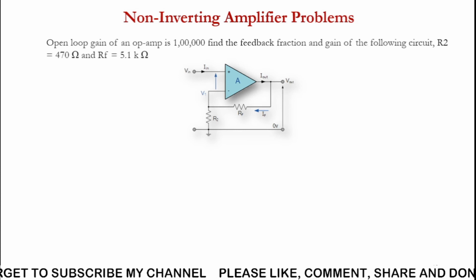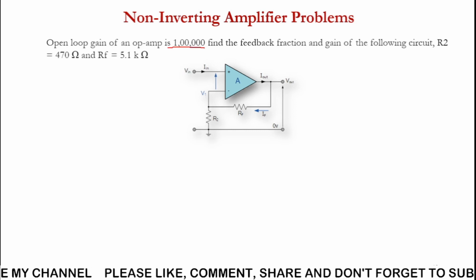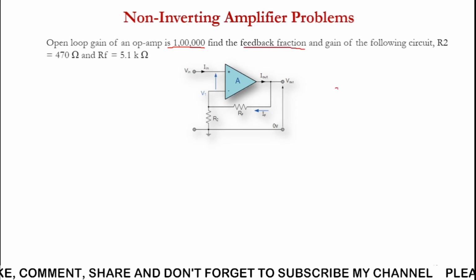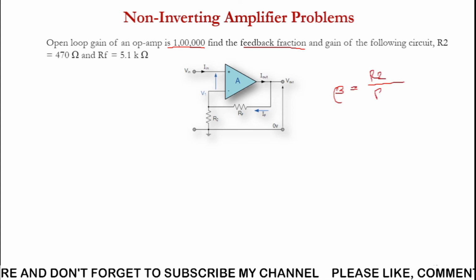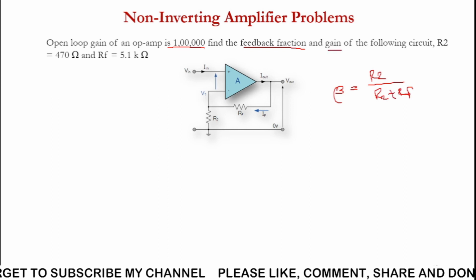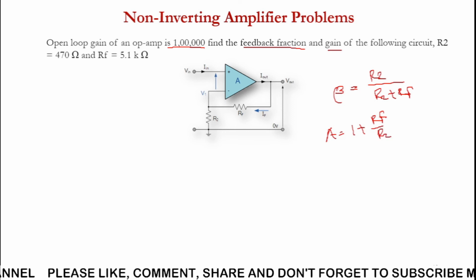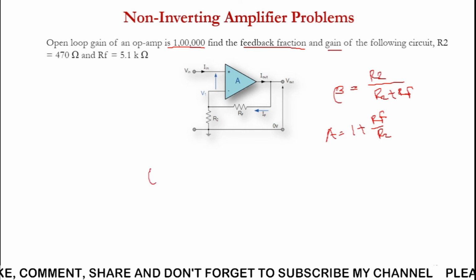So look here, a non-inverting amplifier problem, where the open loop gain is 100,000. The open loop gain does not matter in this problem because we are talking about the closed loop circuit. We have to calculate the feedback fraction beta, which is equal to 1 upon A, or equal to R2 divided by R2 plus Rf, and the gain. R2 is 470 and Rf is 5.1 kilo ohms. Beta is equal to R2 divided by R2 plus Rf, and A is equal to R2 plus Rf divided by R2, or 1 plus Rf divided by R2. Keep the formulas in mind.